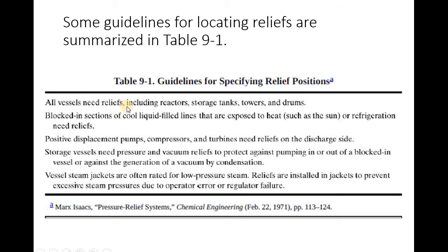All vessels need reliefs, including reactors, storage tanks, towers, and drums. All of them. So don't tell me that storage tanks don't need or that drums don't need. Okay, all of them. Blocked-in sections of cool liquid-filled lines: where there's a possibility to have a liquid line blocked and exposed to heat such as the sun, that means it needs what? It needs reliefs.